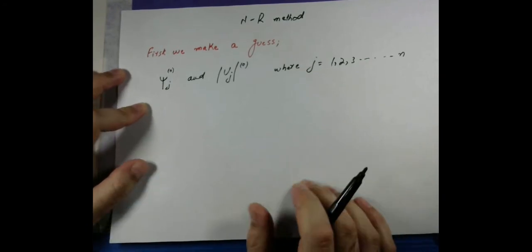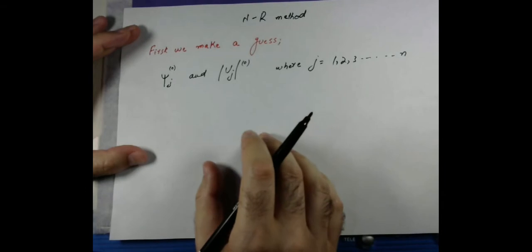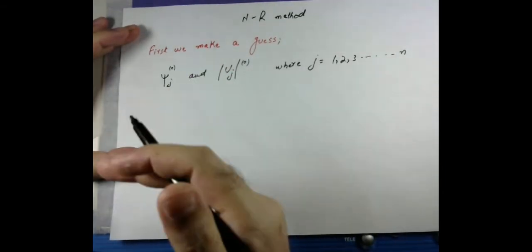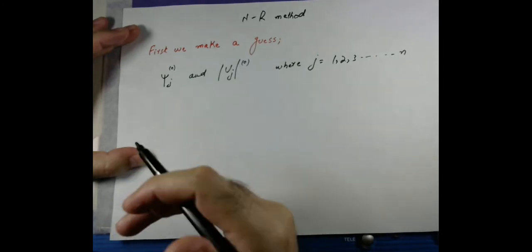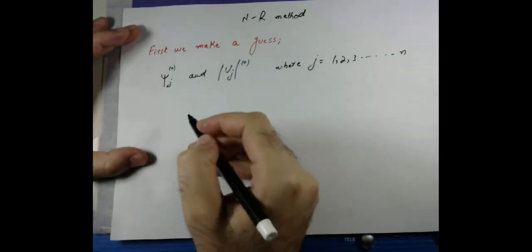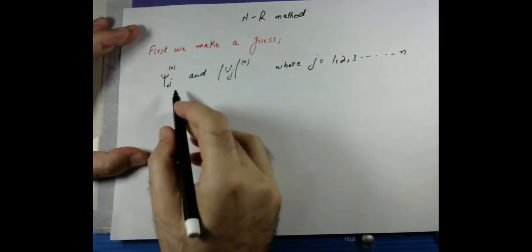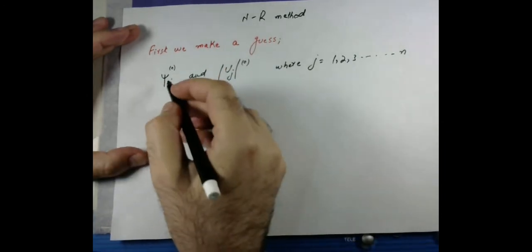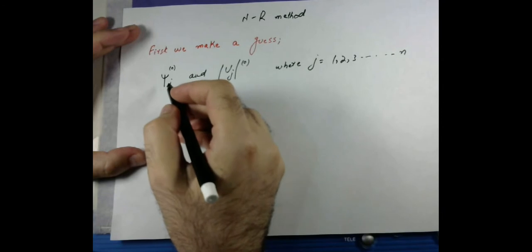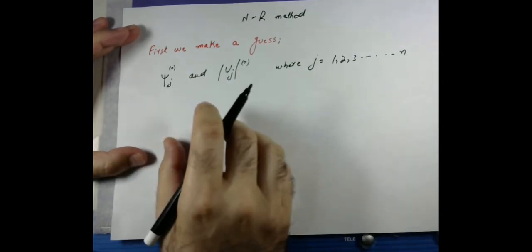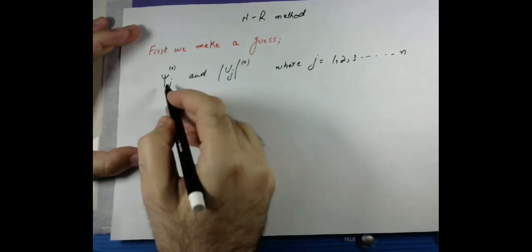However, the difference between these two methods is that in the Gauss-Seidel method, we put the initial guess and then determine the next steps based on it. But here, as this is a guess, obviously there is some error in the guess. So in the Newton-Raphson method, we also determine the error in the first guess.